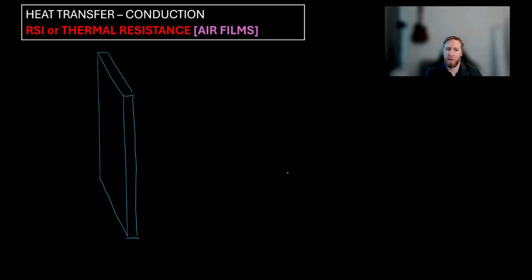Now, one thing to add just a slight amount of extra complexity to it is what's called an air film. Now, the thermal resistance is mostly provided by the separator, by the wall itself. However, if you think about how heat transfers from the surface of that separator to the environment, let's say this is the interior, put TI, we've got air that's flowing around and there's convection currents.